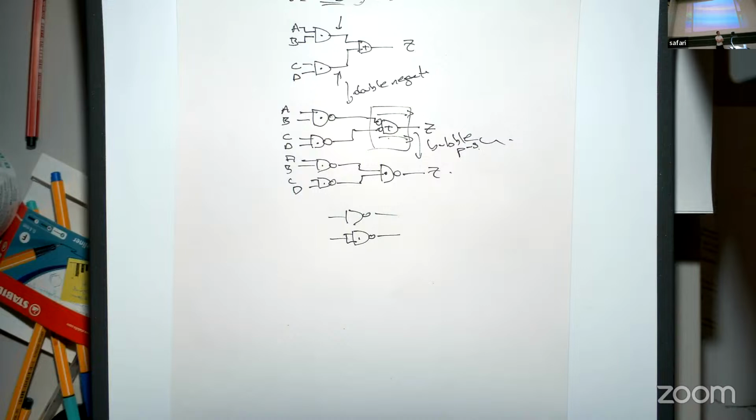You realize that you have a number of instructions which only need 1 register. You don't want to make an R1 type, R2 type, R3 type, because you say, if it fits into one of the other types which I needed, I'll live with it. The best example are the load word and the store word, which always have an immediate in it, even when we don't need it.